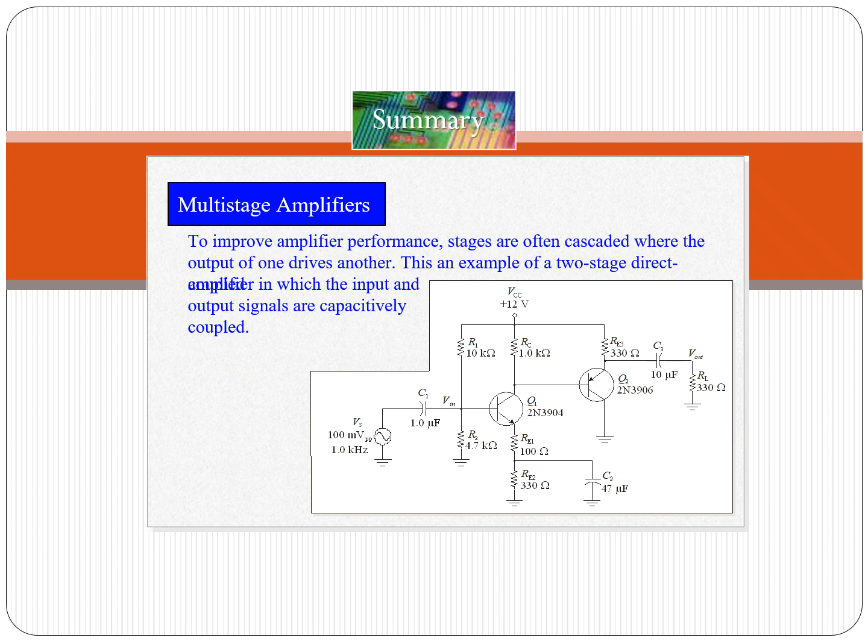In the circuit, we can see that we have stage 1 and stage 2. In stage 1, we have Q1, and that's a common emitter amplifier. It's using an NPN transistor. It says right there 2N3904. And in stage 2, Q2 is a PNP amplifier using a 2N3906. It's capacitively coupled via C2. Again, I'm just describing the circuit from everything we've known so far. And the stages are either directly coupled or capacitor coupled, depending on the design goals.